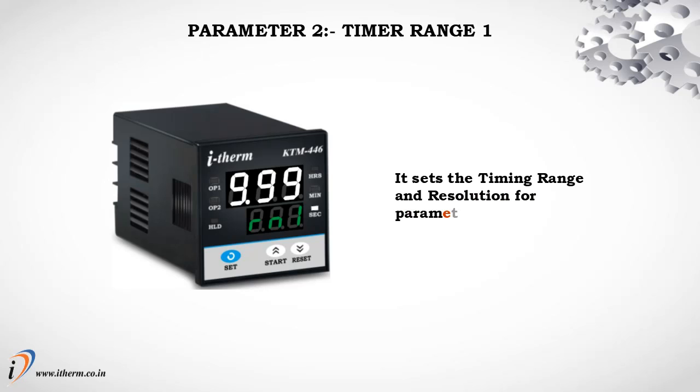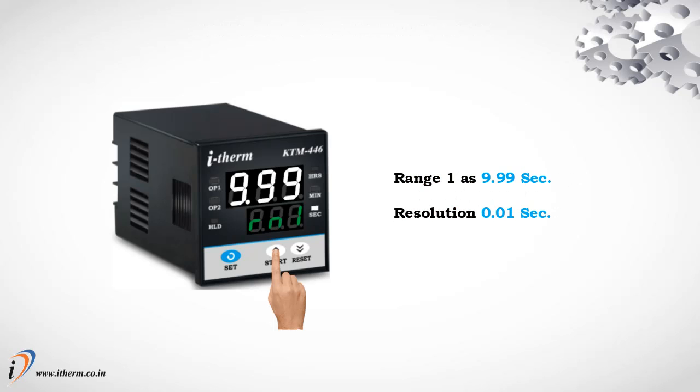Parameter 2. Timer range 1. It sets the timing range and resolution for parameter set time 1. Range 1 as 9.99 seconds, resolution 0.01 seconds. Range 1 as 99.9 seconds, resolution 0.1 seconds. Range 1 as 999 seconds, resolution 1 second.